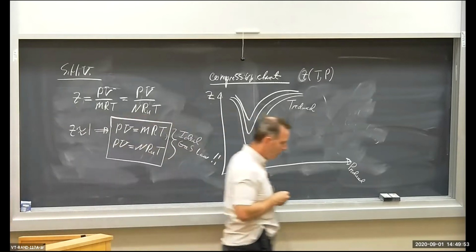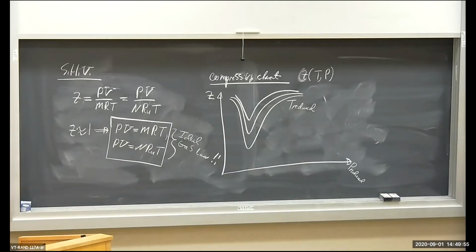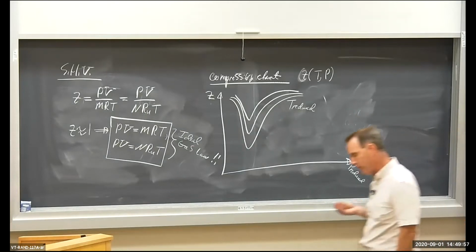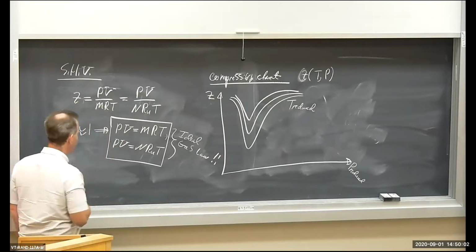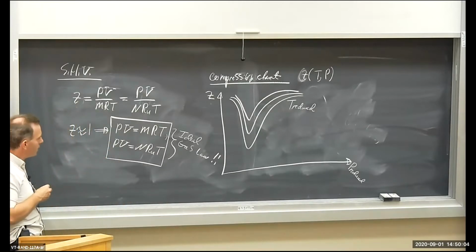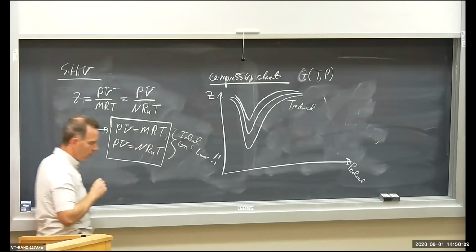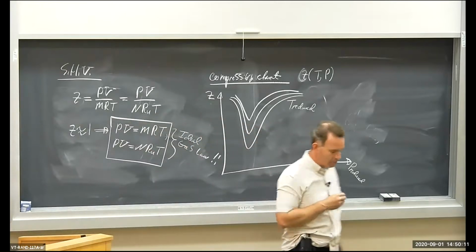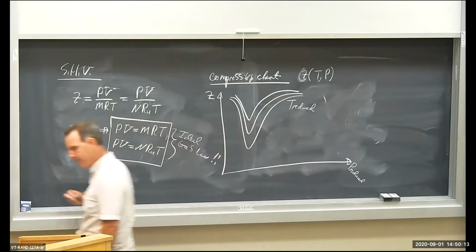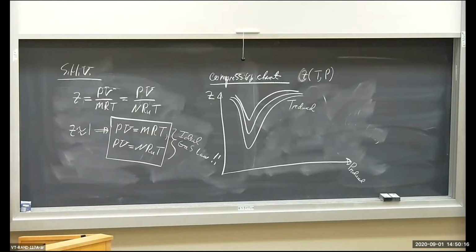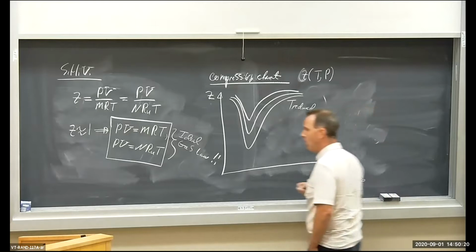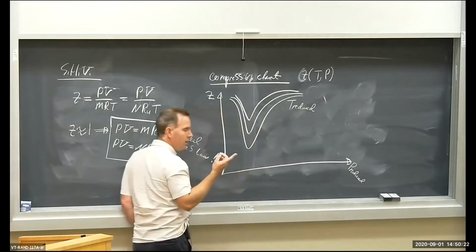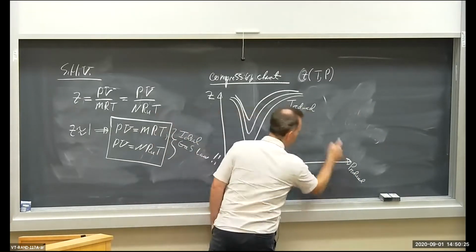So when we have a good temperature and pressure range in which Z is 1, or nearly so, then the relationship between pressure, volume, temperature, and mass becomes very simple. And we can calculate properties for superheated vapor with relative ease if Z is approximately equal to 1, okay? Now let's figure out under what conditions Z is approximately equal to 1. First of all, let's define what we mean by reduced pressure and temperature.